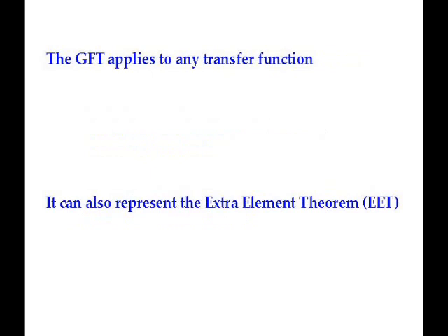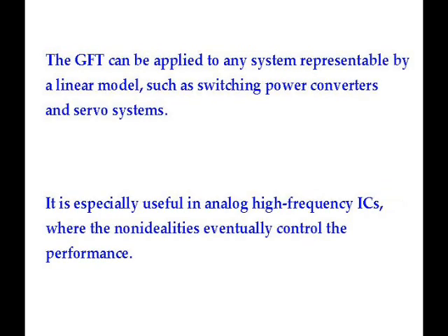The GFT applies to any transfer function, including not only voltage and current gains, but also transfer gains and input and output impedances. It can also represent the extra element theorem to spotlight exactly how one or two selected elements affect the system performance. The GFT can be applied to any system representable by a linear model, such as switching power converters and servo systems, and is especially useful in analog high-frequency ICs where the non-idealities eventually control the performance.